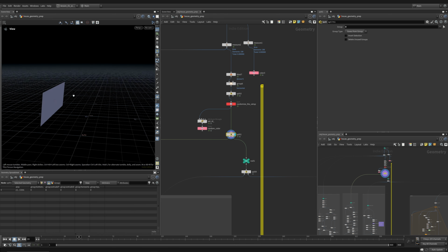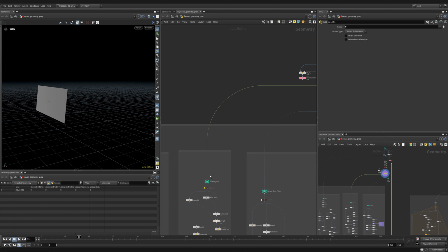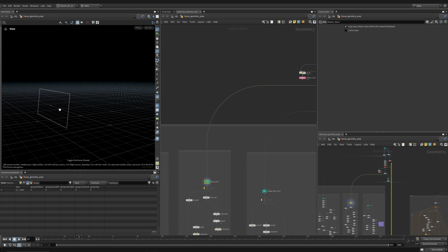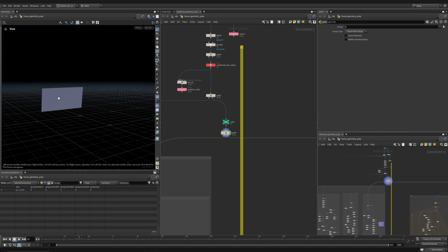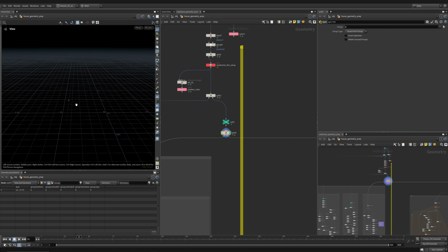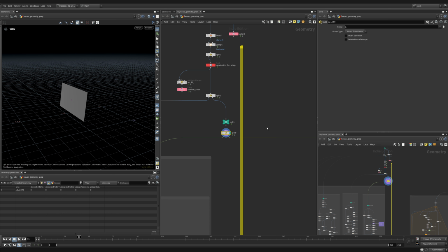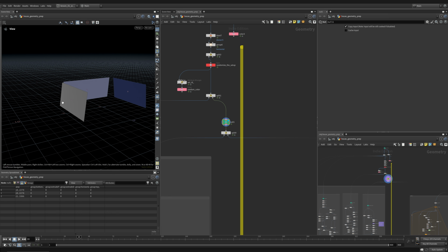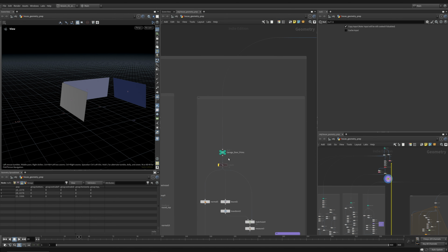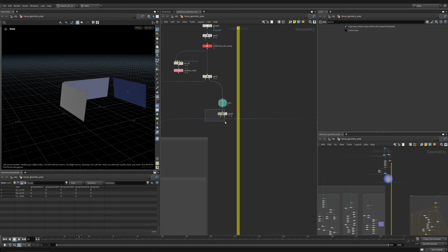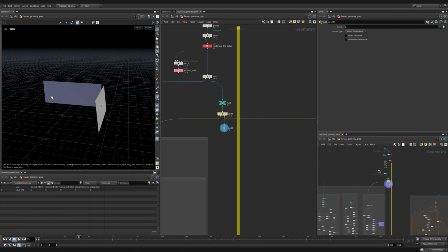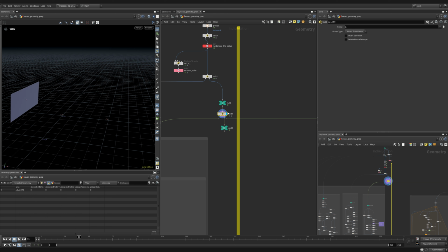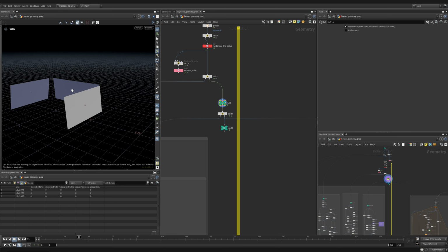And we're able to use, for example, this one we split out, and primitive number 0 is always going to be, it looks like a door. And then we'll split it out here, and it looks like we have primitive number 1, which is now being renumbered because it's the only primitive. But this one is being split and say, okay, take primitive number 1 and always make it a garage door. And then here we're taking the other 2 primitives, which is now 1 and 0 because it's been renumbered. But from this input split geometry, it would actually be 0 and 2.